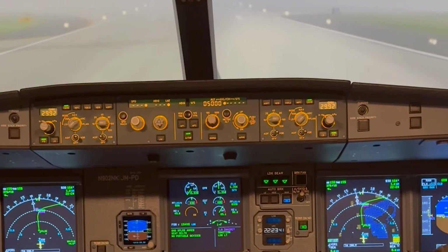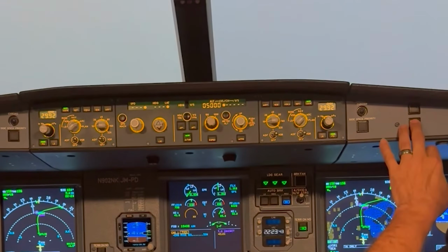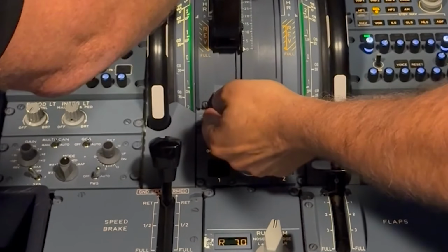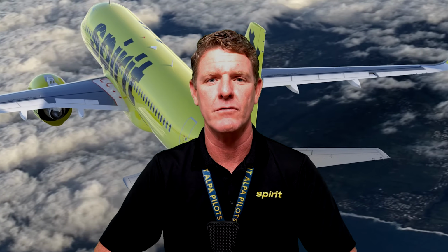We will then follow it up with a discussion on considerations and differences for an engine failure without damage leading to an engine relight in flight. We recommend that during the upcoming engine failure demonstrations, you follow along on your AFB step by step to reinforce your knowledge of an engine failure after V1.